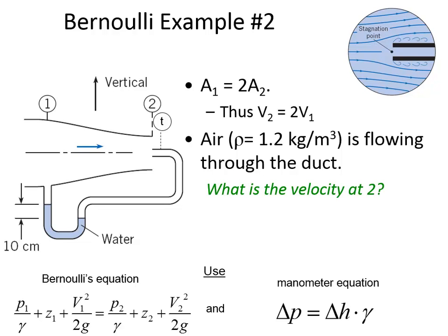The velocity inside the tube is 0 because it's a stagnation tube. Conditions are static in that tube. The elevation is the same between location 1 and this location right inside the opening of the tube. So that enables me to calculate the pressure in the tube as a function of the pressure at 1 and the velocity.